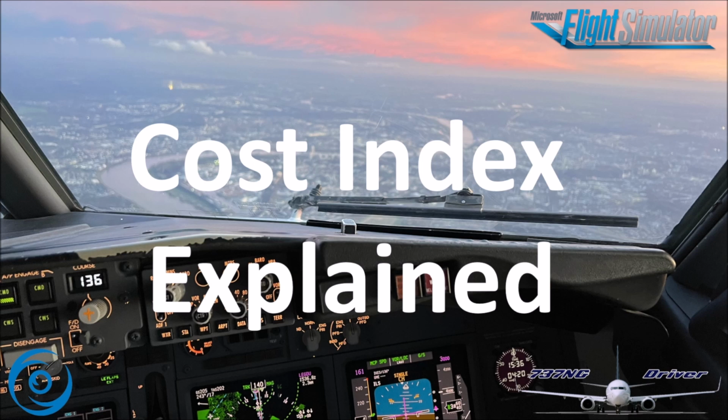The pilot will generally enter the cost index into the flight management computer, and together with the remaining performance data such as the weight, the winds, etc., the FMC is then going to calculate the most economical climb, cruise and descent speeds. What can be said in general is that for all models, entering 0 as cost index results in the maximum range airspeed and minimum trip fuel, while conversely entering the highest cost index is going to give you a minimum trip time, so a cruise at the maximum speeds possible in the airplane.